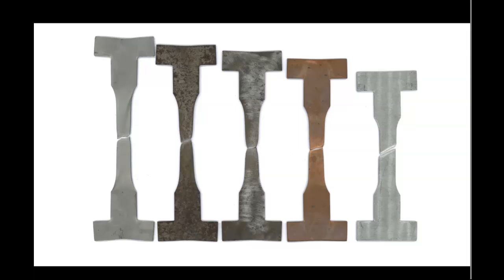When we look at metals, the non-stainless steels, so annealed and cold rolled, they display quite a defined necking, right? And this necking is extended from the shear zone some distance away. So it's not coming from the T clamps or T flanges, but it's actually quite localized.